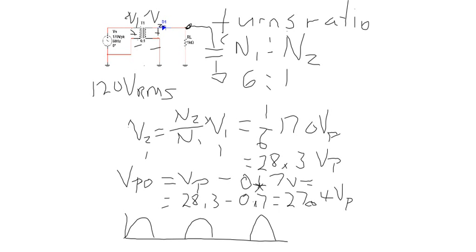During the upswing of this voltage, the capacitor is going to charge, and when the voltage coming out of the diode starts to decrease, the capacitor tries to hold it up. If it doesn't make it, it's going to tail off, and that's usually more of a straight line. At an angle now, it's not straight across, it is decreasing. So that's closer to a DC. What you would see on the oscilloscope might look like this. Smaller eraser.